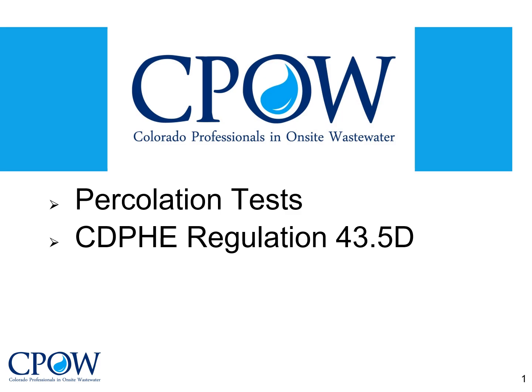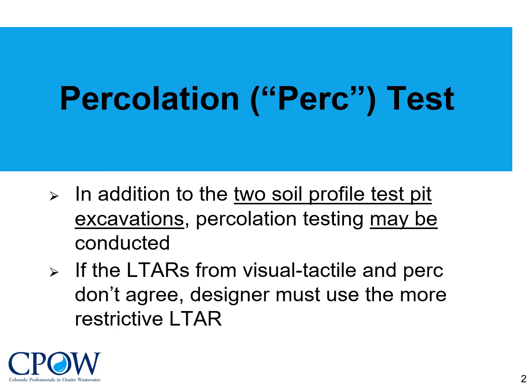This is the Colorado Professionals in On-Site Wastewater presentation on percolation tests. Percolation tests are covered in the Colorado Department of Public Health and Environment Regulation 43 and Section 43.5D. Regulation 43 requires a visual tactile analysis of the soil in at least 2 soil profile test pit excavations.